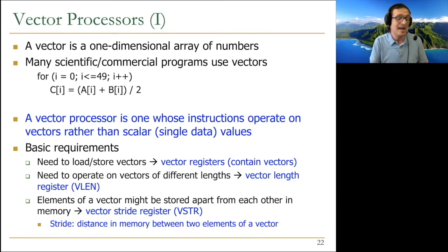The elements may actually be every nth word: element 0, element n, element 2n, and so on, could be the elements that we want, because that's how the data is stored in memory, as we will see in a little bit. So you should be able to specify how you load this from memory, because vector loads operate by taking one base address and incrementing it.